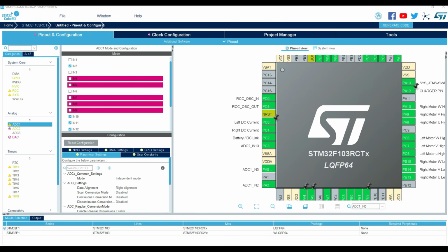So it is protection for the battery. And for FOC feed forward, the PWM duty is automatically adjusted by measuring the voltage, and it also tells the state of charge, the battery percentage, how much is charged or already discharged.